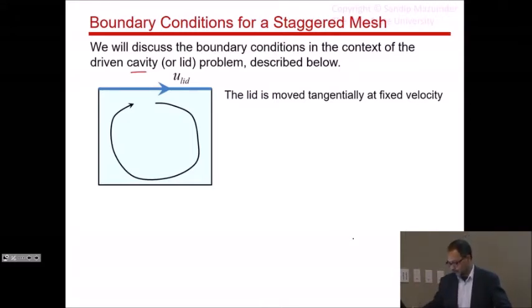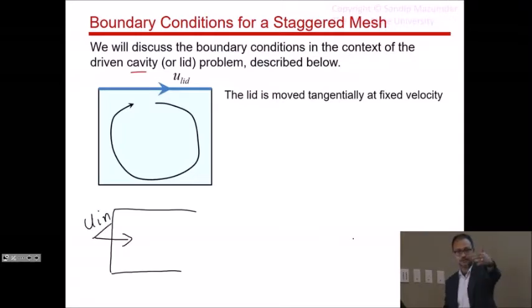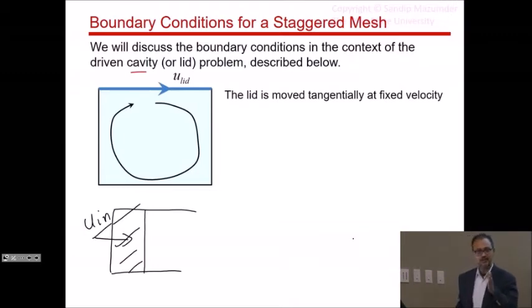Another question that students often ask me: what's the difference? You mentioned that if this moves normal, then it's a moving mesh problem. What if this is an inlet? There again, the fluid is moving normal to the surface. But this is not a moving mesh problem, because the volume you had right next to the inlet stays the volume. The volume is not shrunk. The volume gets shrunk only if it's a solid wall and it's moving.